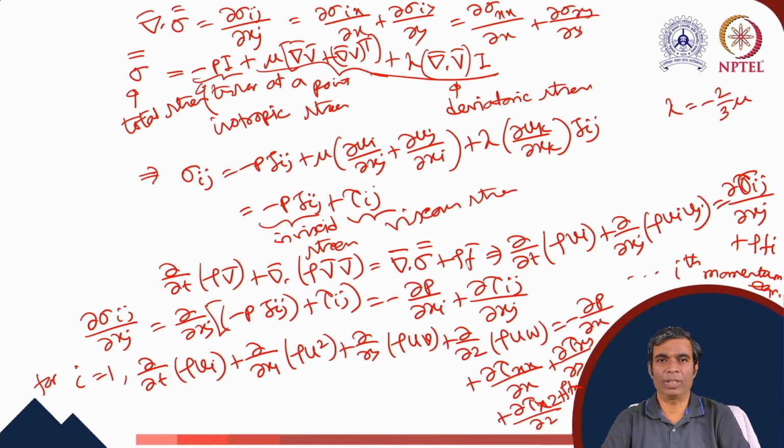Something I forgot to mention at the beginning: all the conservation equations which we write, I have written already 2 equations, the continuity equation and the momentum equation. I emphasize here that in fluid mechanics, we use the Eulerian approach. When we discuss the Eulerian approach, we focus on the points and not on particles. So particles are discussed in solid mechanics and points are discussed in fluid mechanics. Because of this, all these equations are written at a fixed point within the fluid domain.